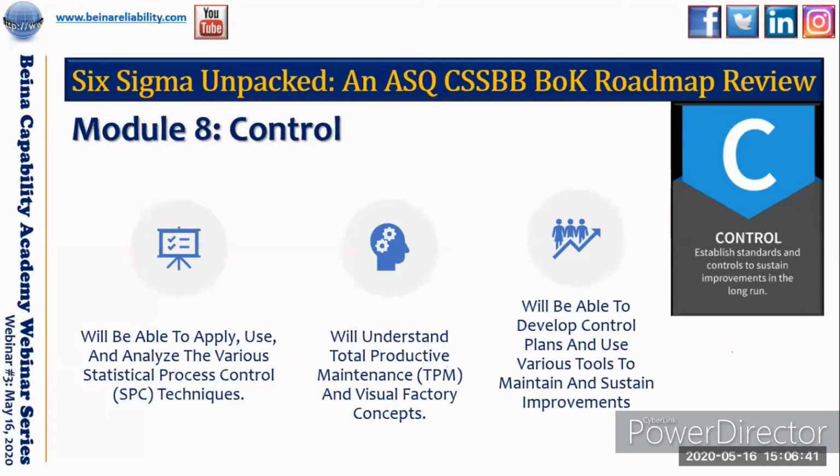And this is where SPC comes in. SPC, total productive maintenance, visual factory. If you go into the core of SPC, you see that SPC helps you know when do I need to come into the system. Because you are running an SPC, say for instance that you have a control chart and you are checking the variation in your output. As you are checking the variation, you see a sudden variation that you cannot explain. You know when to come in.